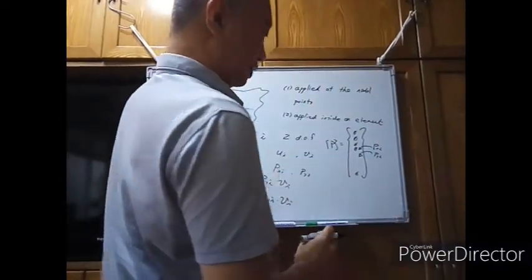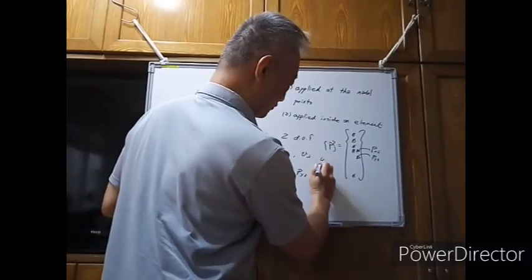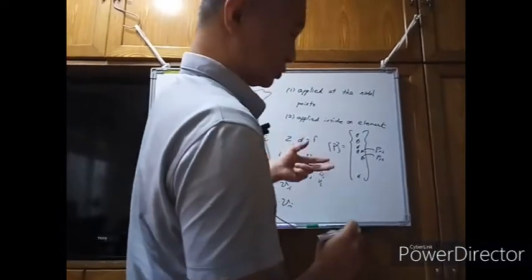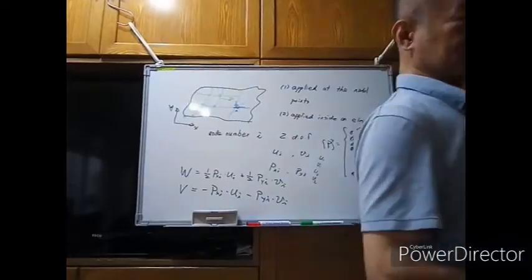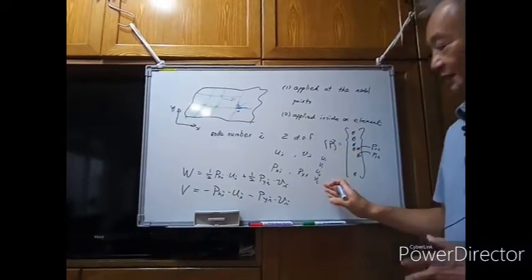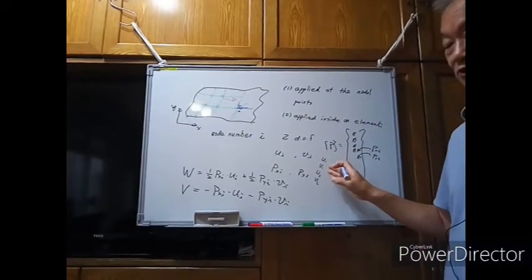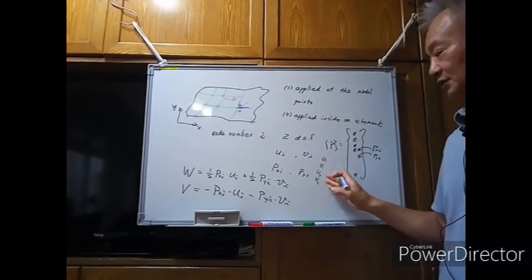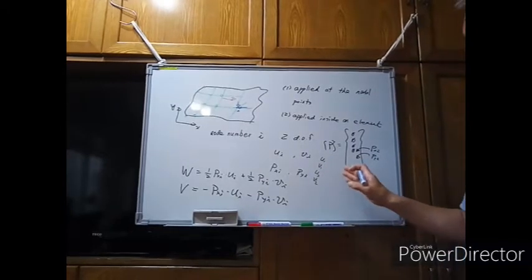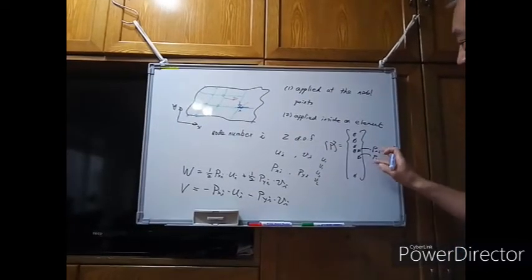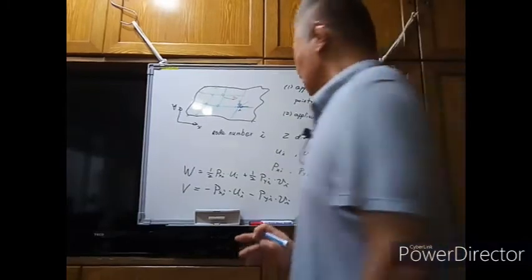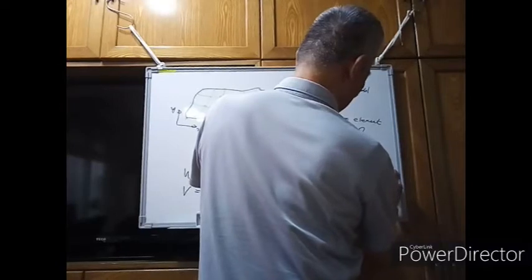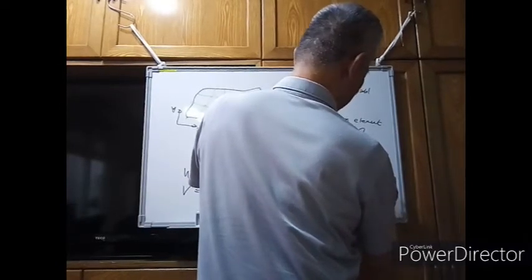Okay, and most of the time we have the U1, V1, U2, V2. So for most programs, the nodal displacements are arranged so that the first two degrees of freedom are the U1, the V1. The third and the fourth elements are the U2 and the V2. So pxi and the pyi will usually go to the 2i minus 1 and the 2 times i.